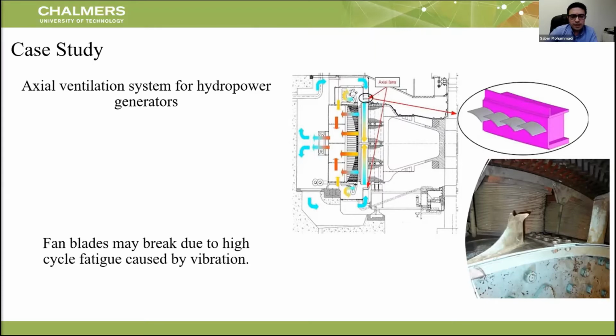The fans used in the main part of hydropower generators are made of bent plates, which are welded on a fan ring or segment to keep the cost at a minimum. They operate in airflow that is highly restricted to the space that is available when the electromagnetic parts of the machine have been designed.